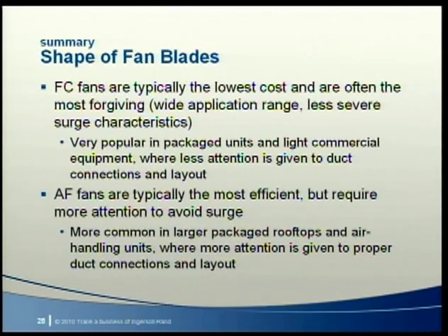Airfoil fans are typically the most efficient, but because of their narrower application range and their tendency to have more severe surge characteristics, they do require more attention to avoid problems. This makes them more common in larger packaged rooftops and applied air handling units, where more attention is usually given to proper duct connections and layout.